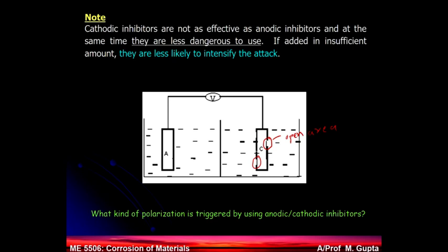It will not increase, because remember, in any wet corrosion, the overall rate of corrosion is governed by the magnitude of the cathodic reaction. Now, by masking 90% of the area hypothetically, you are reducing 90% of the cathodic area. So now you have a very small cathodic area. Same thing as in the shipping industry, a ship made of steel, but the rivets are made of copper.